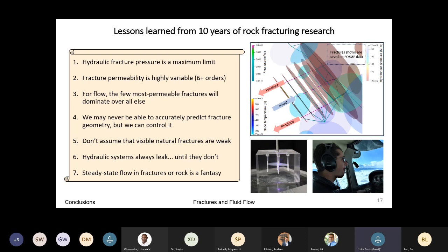And then this is kind of a fundamental lesson in a way: we can't really predict fractures, not very well. We have models that give us good estimates for what the general length might be, height, total aperture. But as far as predicting where an actual fracture is going to go, asymmetry left to right of the well, that predictive capability is a very difficult to achieve goal because we simply don't have the fidelity of in situ data to really be super precise with those predictions. So it's better to design systems that aren't overly reliant on accurate predictions in my mind.